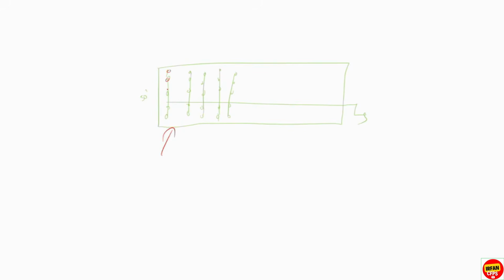For example, in that length, you are getting all these sprinklers to be considered. So till here, I just extend this line. And then now 1, 2, 3, 4, 5, right? 6, 7, 8, 9, 10. So this is my rectangle. Again, I draw the rectangle. Now, since the cross main is here, not in the wall, right?